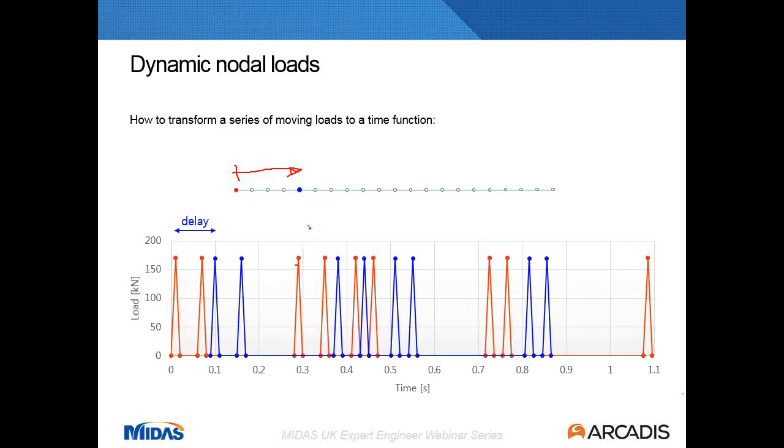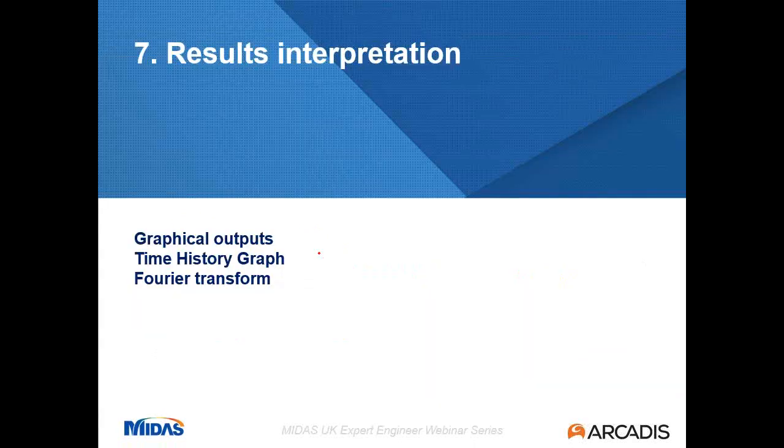I'm going to jump back to the presentation now and go into the next section. That's results interpretation. That's very important for a couple of reasons. The first is that you want to make sure that your analysis is right. And secondly, because you need to be careful when extracting the results, so you're getting the peak values for forces, deflections, and accelerations.